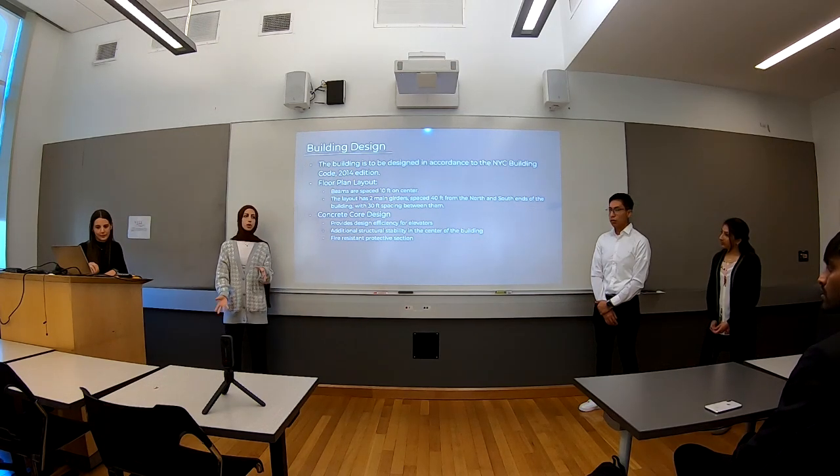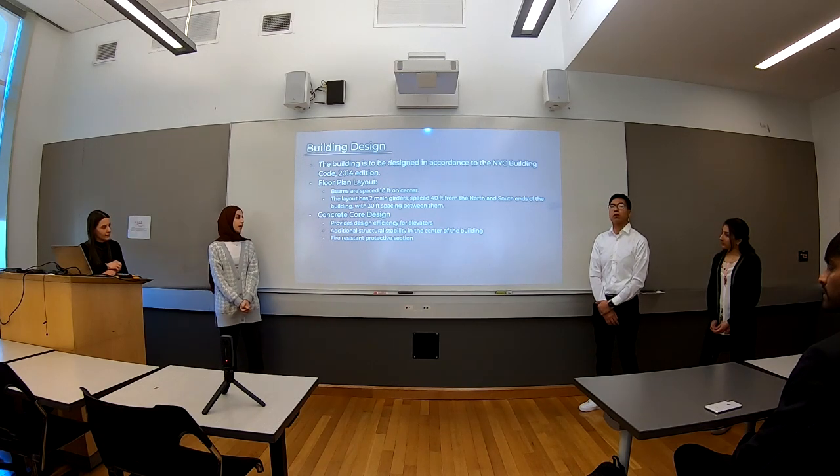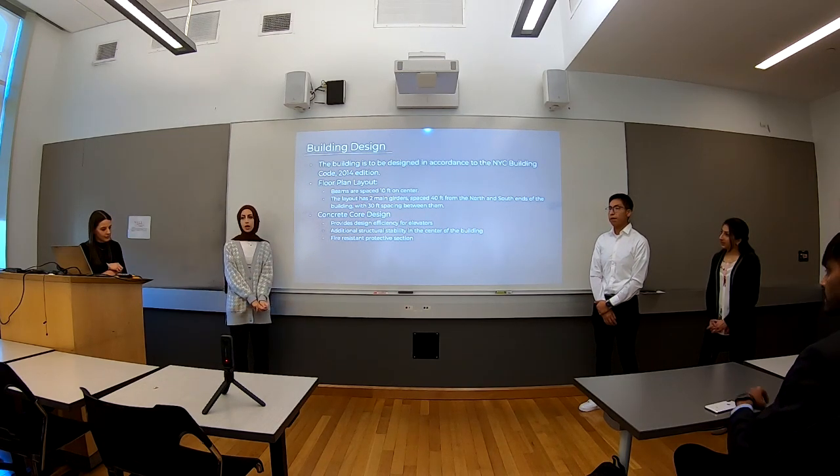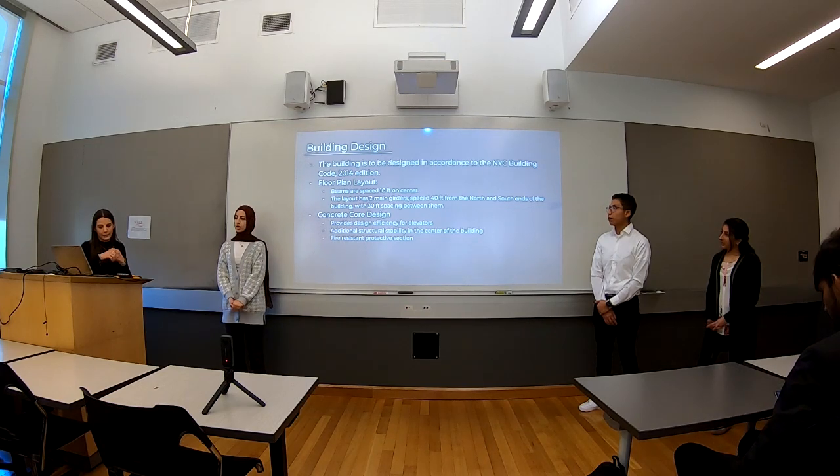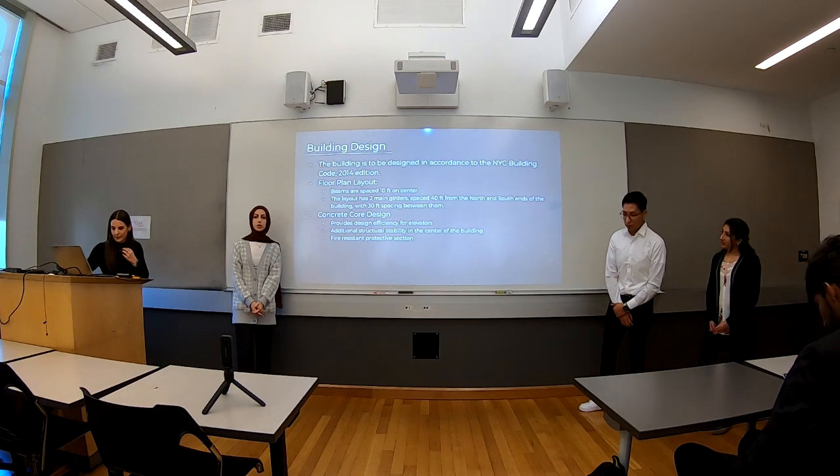And for our core, we decided to go with the concrete core, and this allowed the most efficient design for elevators. It provided extra fire protection, and it also added some structural stability to the center of the building.